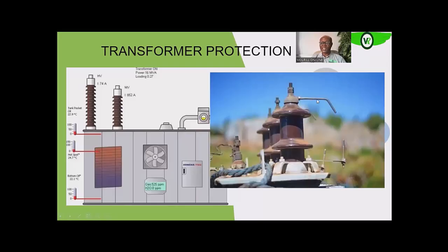Remember, air is an insulator. Now, once there is a surge, which is a very high voltage event, it can cause the breakdown of the dielectric strength, or the insulation, of the air between these two contacts.